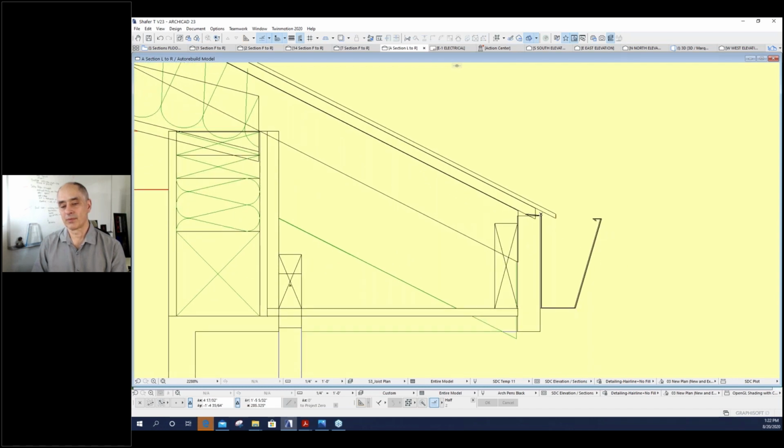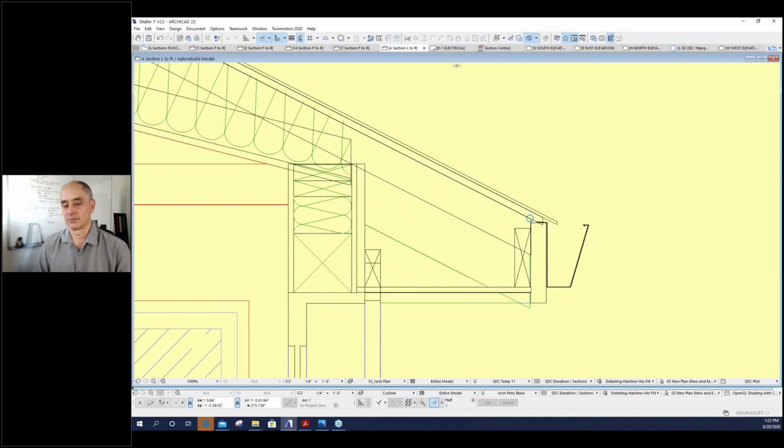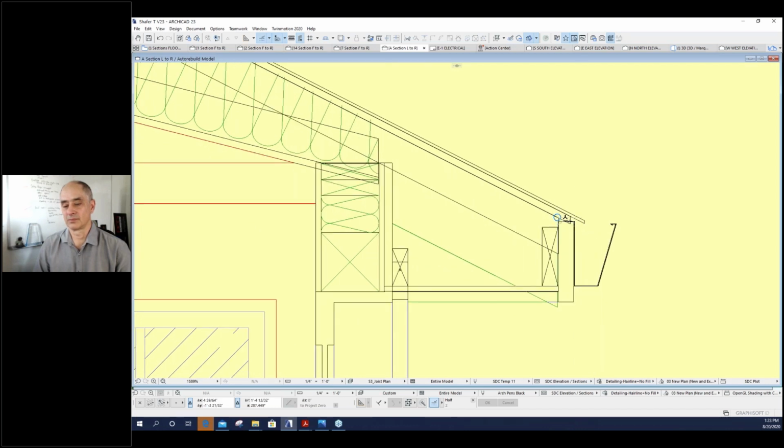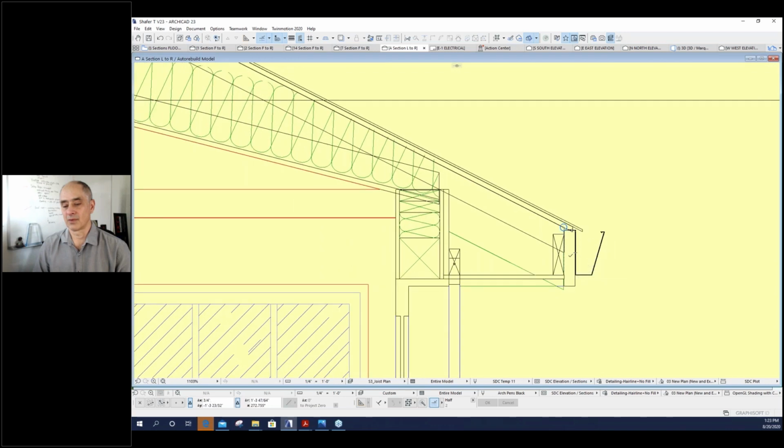And if you don't put the plywood and the comp, and you just work off your roof outline with the roofing material on that, the top of your fascia board shows. Mm-hmm. And in some projects, I'll even put in the drip metal. I have that as an object that we've created. You have to use two different ones.